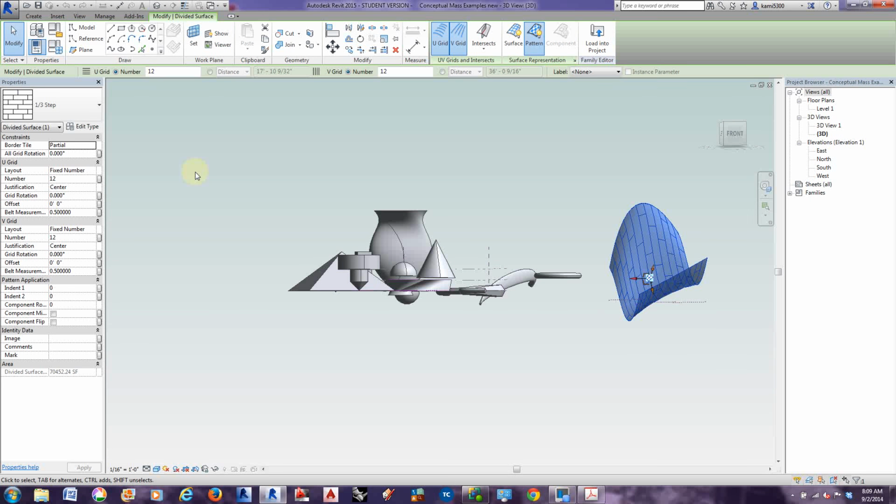Everything you load into Revit is a three-dimensional parametric object. A door, if you want to change the width of the door, that's a parameter that tells it to change the width. So starting to understand how these parameters work, hopefully you can then start to create your own families, or understand enough at least to open up an existing family, maybe make some custom changes to it and load it back into your project, so that it's not just a standard out-of-the-box Revit door or something like that. All right.